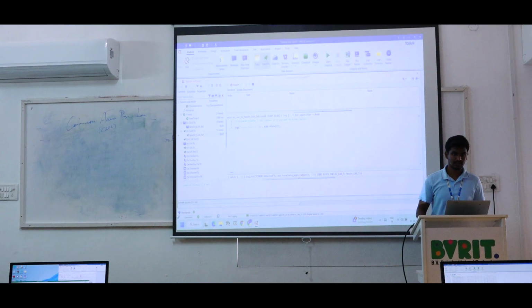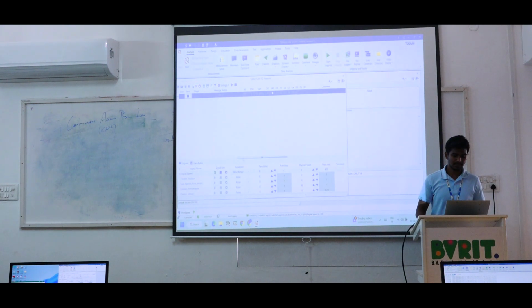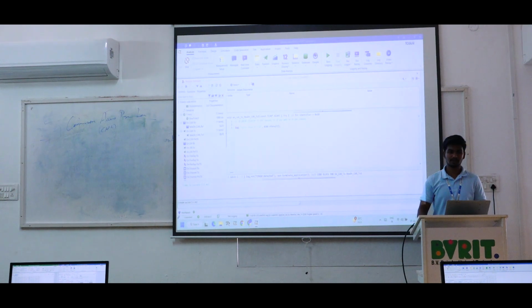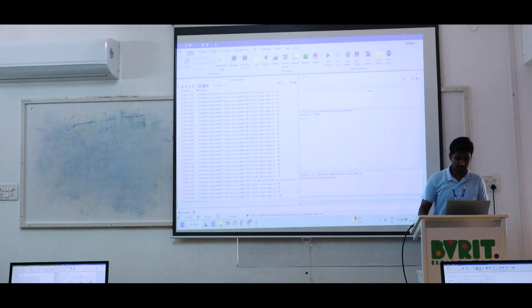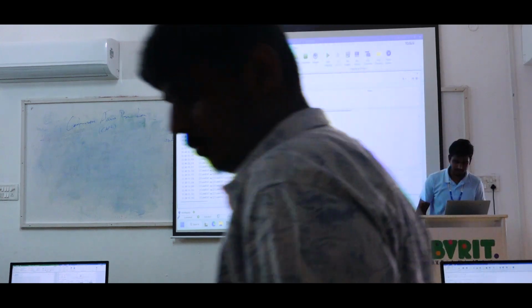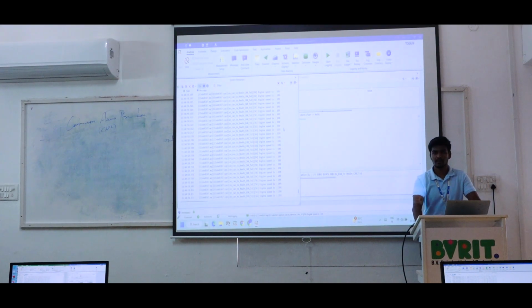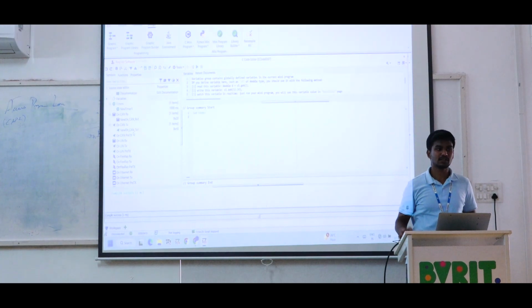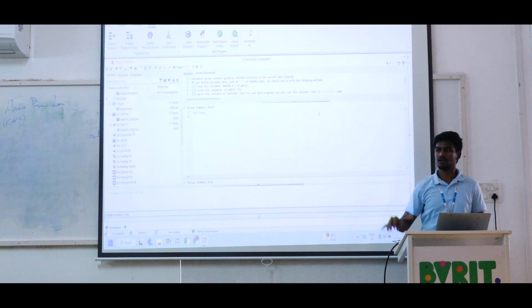Just to check, in this transmit window, open the transmit window, check whether the message is running or not. Please check whether the signal is also running or not. Okay. So now both are running, which means CAPL scripting is running. Afterwards go to the messages column. It is showing that TX of engine speed is running. Okay. TX means what we transmitted in this tool or in this system.